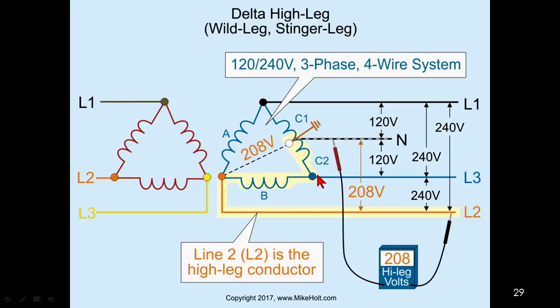And then when you have a 3-phase load, it distributes among all the lines. So you'd have to balance 3-phase loads on all the lines, line to line. So you have to put in your panel schedule, and we have to tell you which breakers go in which positions in that panel. Because you just can't drop in breakers and start putting in loads like you would on a Delta Y transformer or Delta Y configuration. So this is something you really have to be aware of.